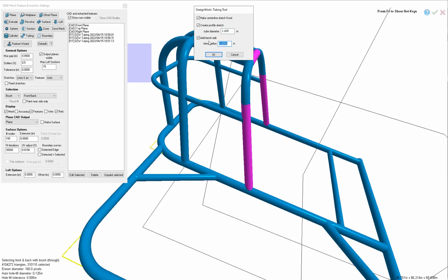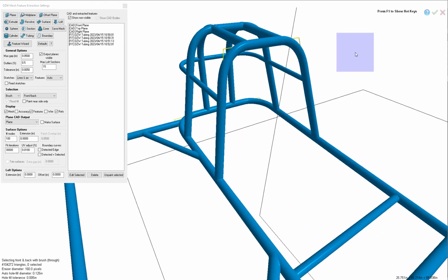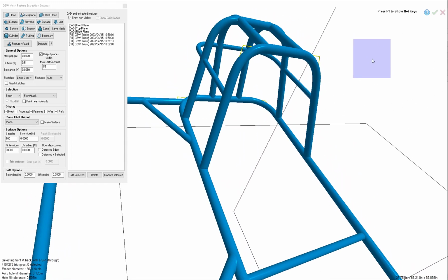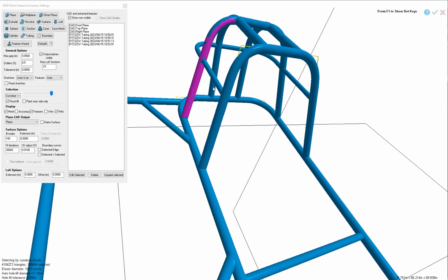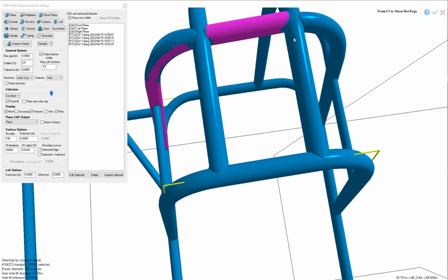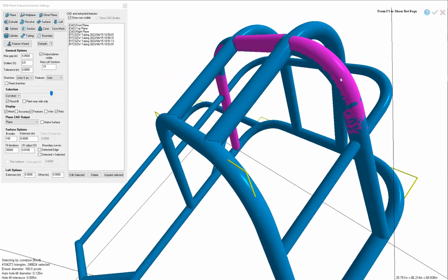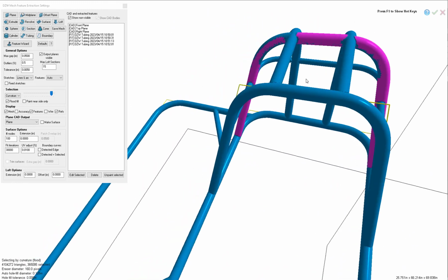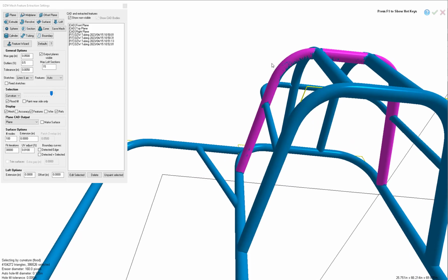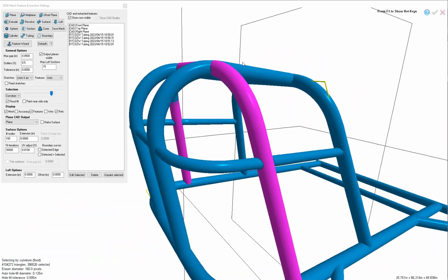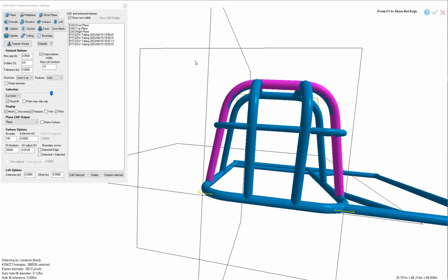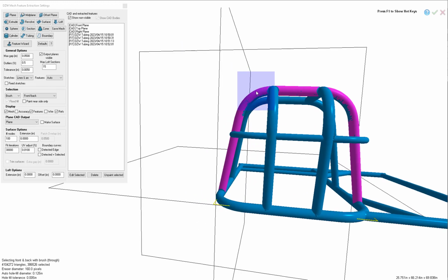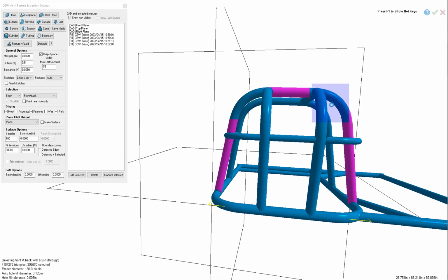And all this can be changed in SolidWorks. We're fixing the straight lines. And if you want to go back and modify this, we'll show you. You can do everything you want to do. In this case, we'll help it. We'll click over here because it found a junction. And then again, we'll get rid of the fillets on there. And then run the tubing tool.